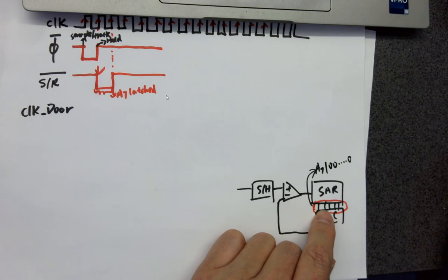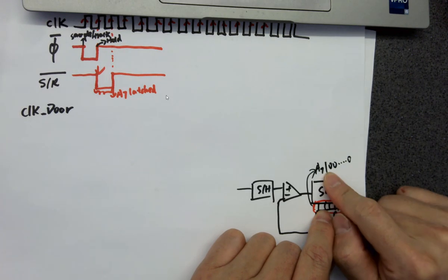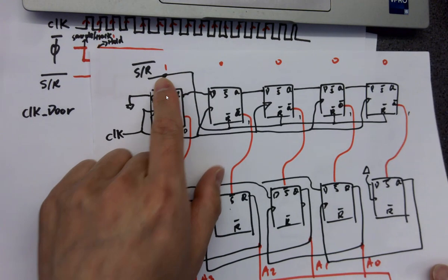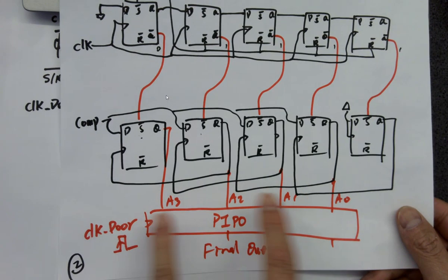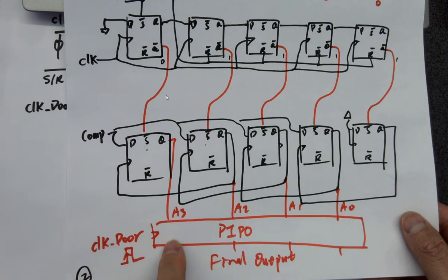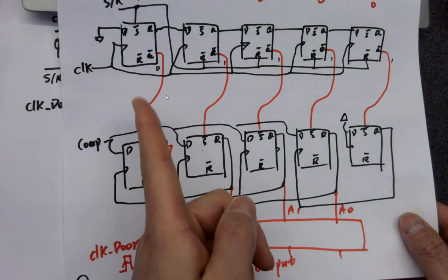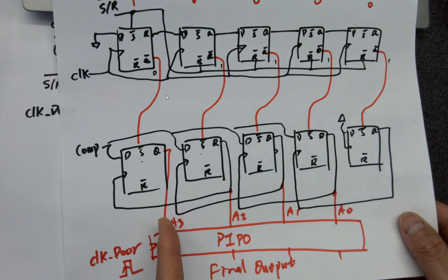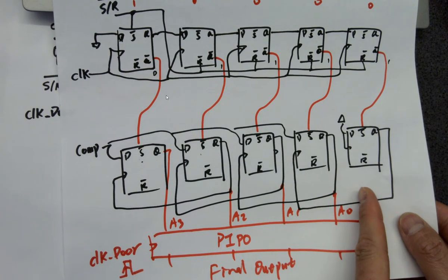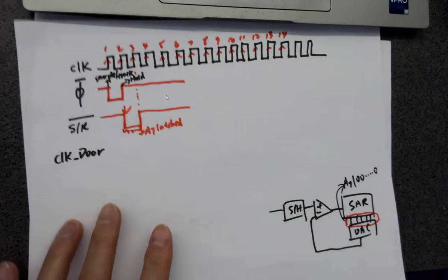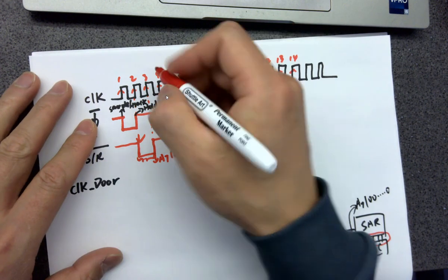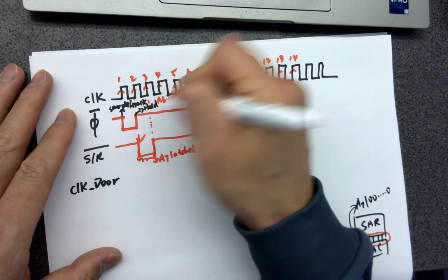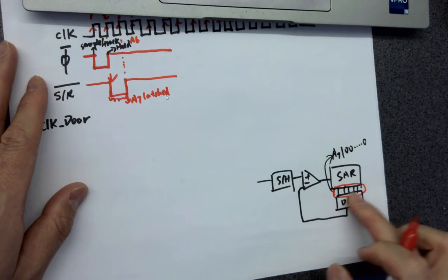Is that true? That one was a one, got set or reset at the very beginning. So whenever you plug A7 in here, I'm having a 4-bit, but just imagine this is an 8-bit. So A7 will be plugging over here, and the previous one will be shifted to the right. So we're getting A7, 1, and 0s. In that case, the following rising edge is going to give you A6 latched into the code over here.